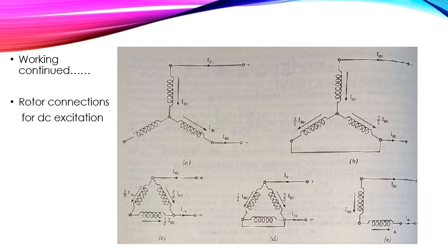Right? So it can be improved when it acts as a synchronous motor. The larger air gap and the increasing excitation EMF per synchronous impedance result in a higher peak synchronous torque. So the synchronous induction motor is provided with a large air gap, as opposed to a plain induction motor.